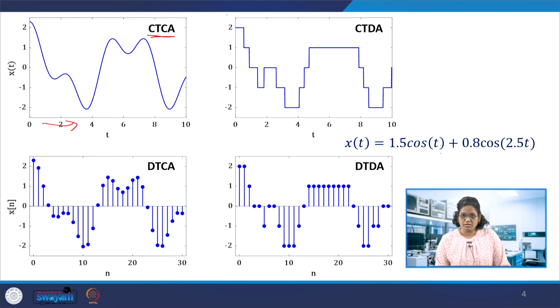When we sample this signal, that is for discretization, the sampling makes the signal discrete at instances 0, 1, 2, 3, which becomes n now. It is a periodic sampling, or uniform sampling. That means the sampling period is equal in this case. The other case can be random sampling, in which the sampling period will not be uniform. Here is a uniform sampling in which this signal is sampled, and we get the same value that we have here at this point.